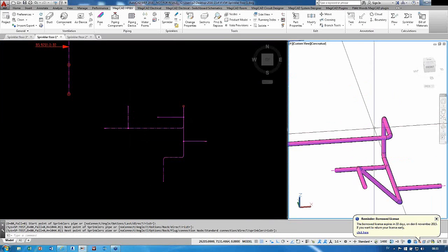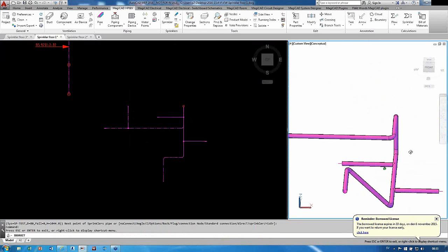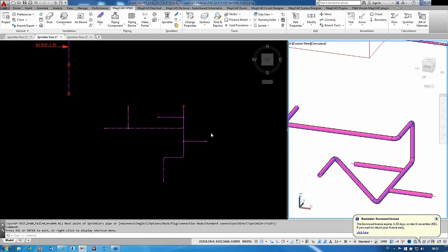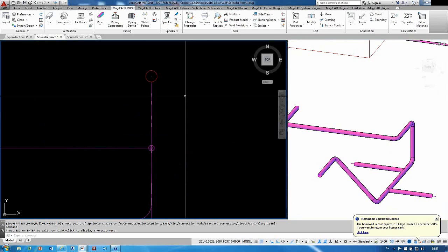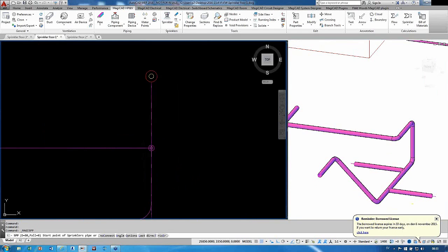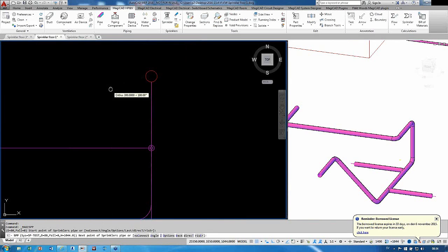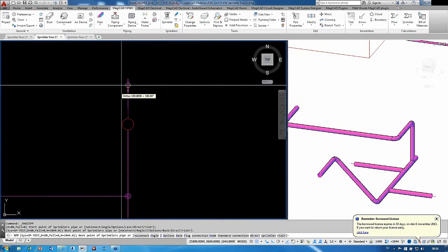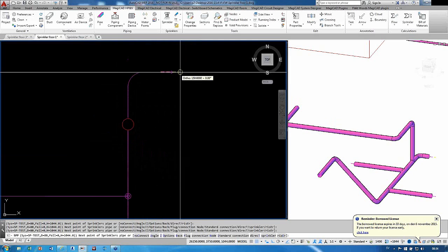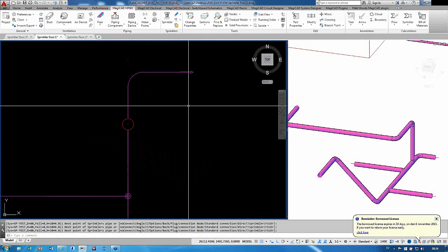And of course, same thing if, for example, we are selecting this one. So I go from a sprinkler pipe, I just select here. Then, do you want to start from the bend at 2044, somewhere at the vertical pipe, or at the bend at 1044? I take the bend at 1044 and I continue to draw like this.